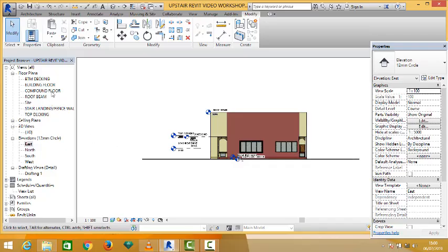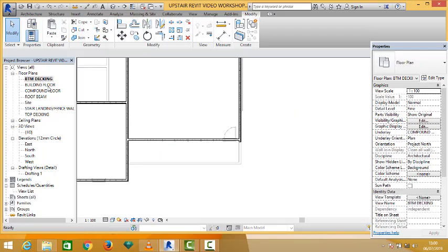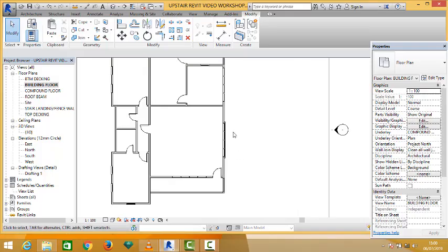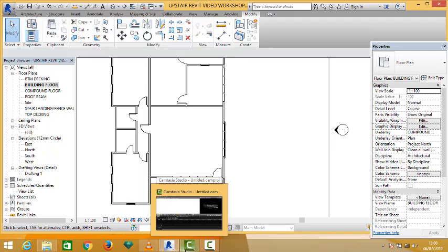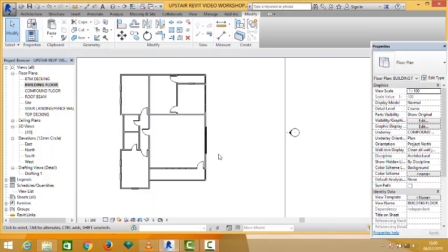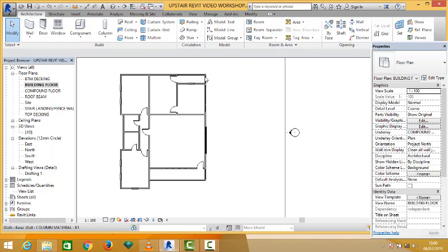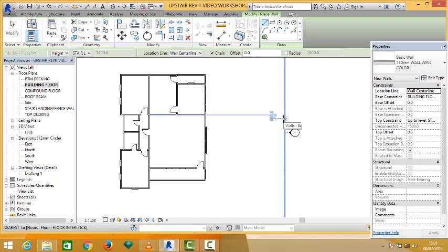So very quickly, our staircase usually begins from the ground floor of our building. So we go to building floor. You know, the suitable width for staircase on residential building is usually 1800, and then you have 150 walls bordering it on both sides. So 1800 plus 2 times 150 gives you 2100. So our optimum spacing for our staircase is 1,800 plus 150 for the walls on both sides. That gives us 2,100. So our boundary walls will take 2,100.